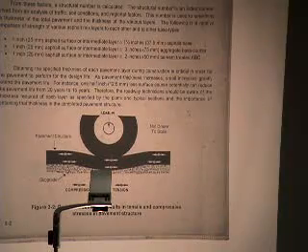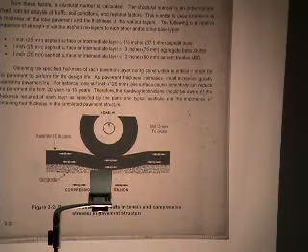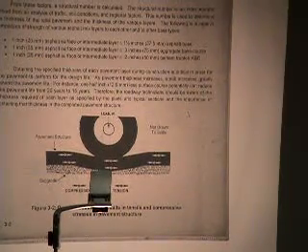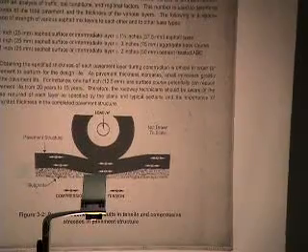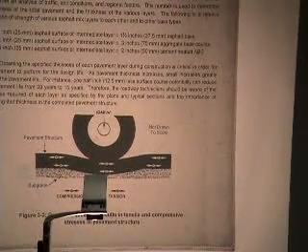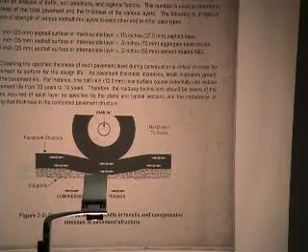And basically, that's the same concept with the pavement. When you're designing that pavement, you want to design it so that you minimize that deflection. And I guess you could build a pavement where the deflection would be virtually zero. But if that was the case, it'd probably be real thick and very expensive. So again, you have to keep economics in mind.